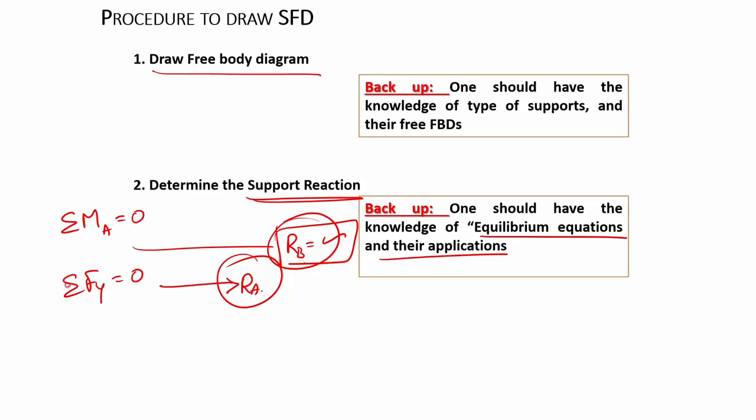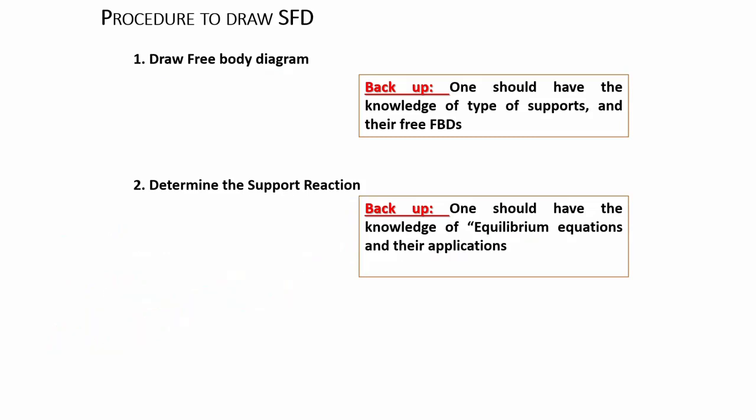And even if any inclined forces or horizontal forces are there, their effects also you can deal with, and that you will come to. Get it? Right. This is the determination of support reactions. Be careful and determine the support reactions correctly. If the support reactions go wrong, then the entire SFD and BMD problem will go wrong.